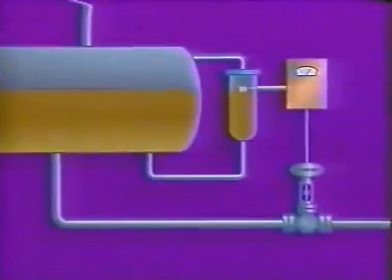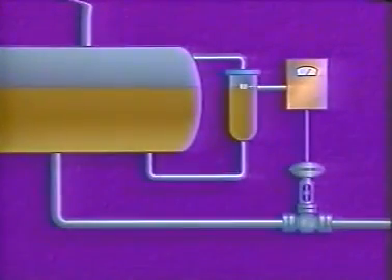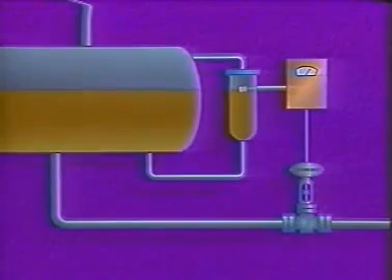This vessel provides a reservoir of fluid for a process. A minimum fluid level must be maintained or the vessel may be pumped dry. Vessel level is kept constant by measuring fluid level with a float and regulating outflow with a valve.